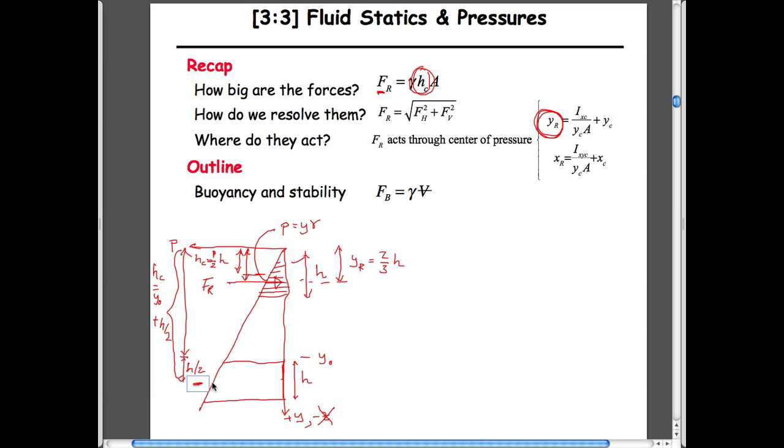And that is that if you look at this pressure distribution at this half-point height, if you look at a dotted line, which I can't draw very well here, and you extend that dotted line up here, then basically you can take this prism here, and you can put it here, and then if you calculate the pressure at the midpoint, this magnitude here, in other words, which goes up to here, then that's the pressure that you use. So that's the reason why you can use this expression for the vertical depth always, even if this plate is inclined, by the way.